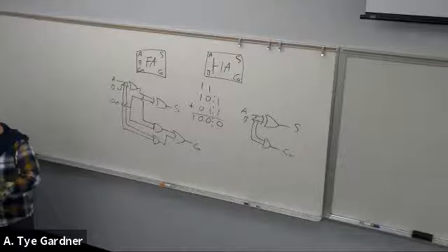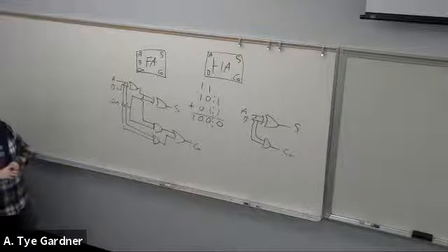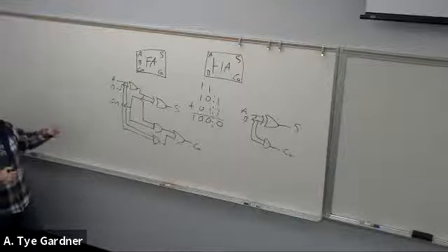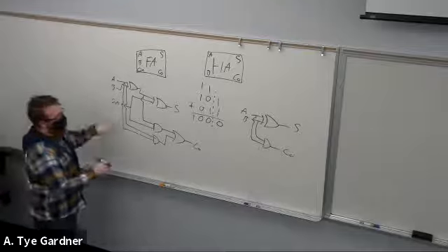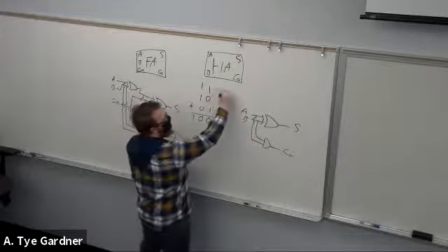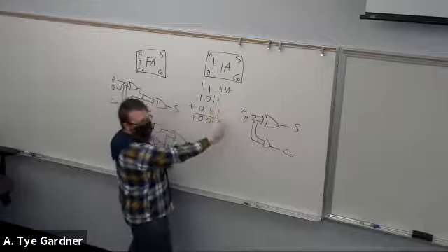So I have a quick question. How does AB and the half adder and then AB and carry in relate with the addition problem you have written, or does it? Yes. So in this circuit, this first column is a half adder because there's no possible carry in the first column.